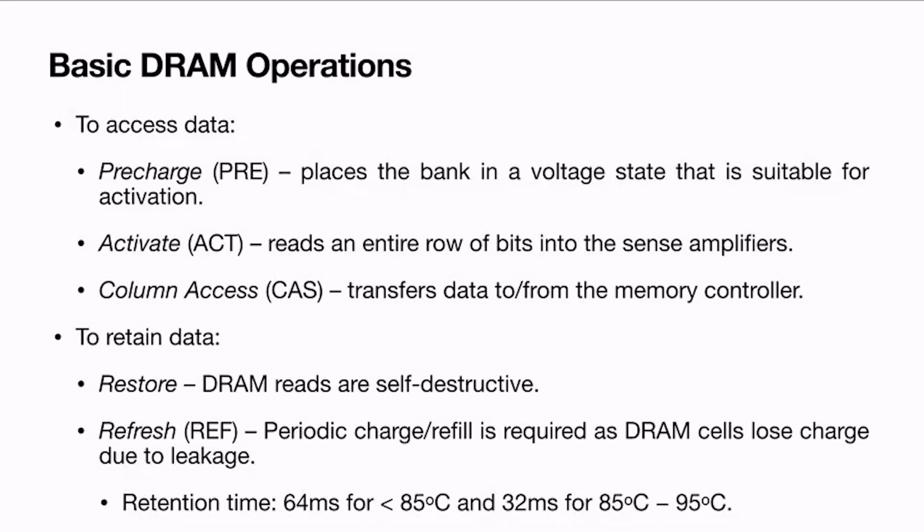That is where people propose multiple optimization techniques to reduce the overheads associated with refresh. Some people are also looking at why we can't replace the DRAM completely and come up with new memory technologies. For example, emerging memory technologies like phase change memory, STT-RAMs and so on. These are different technologies people are coming up with. And there are some processors which are actually using STT-RAM or PCM based memories, but they're not completely replacing the DRAM. They consider DRAM and some part of the memory using these emerging memories, where you don't need any of the overheads associated with refresh.